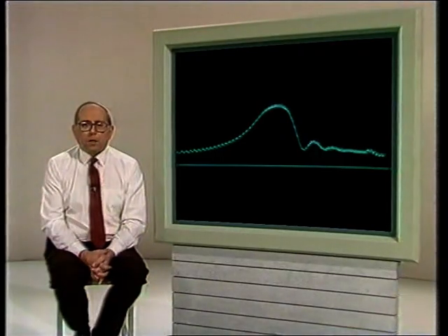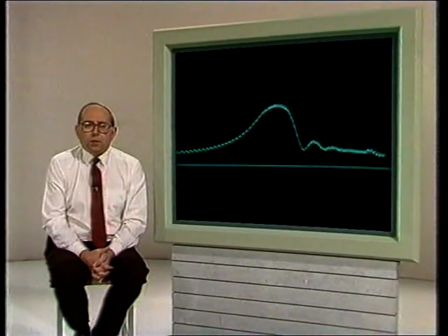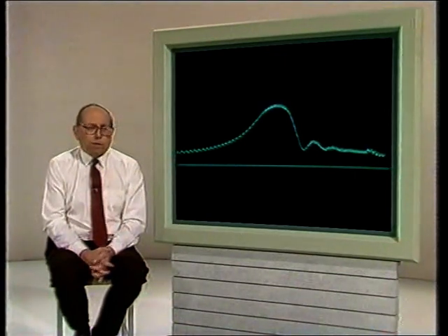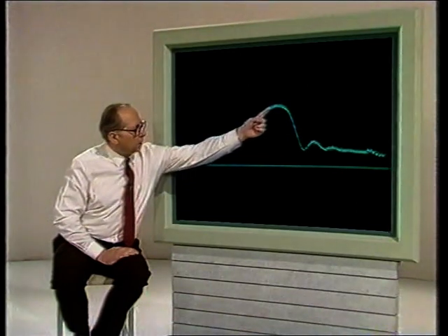The transmissibility curve is a vital piece of experimental information for the designer. It shows the relative magnitude of the output response in relation to the input. It also shows the resonance frequency. For example, for our experimental setup, the transmissibility at low frequencies is about 1, rising to about 6 at resonance, and falling at higher frequencies.